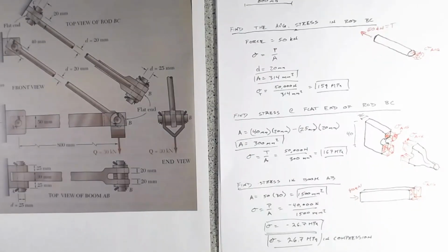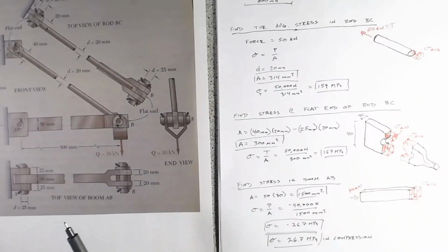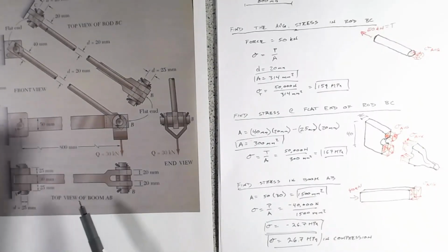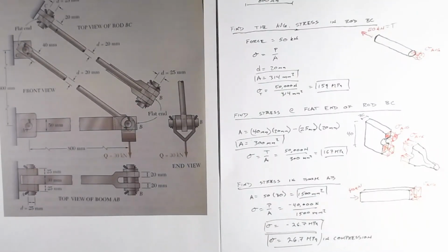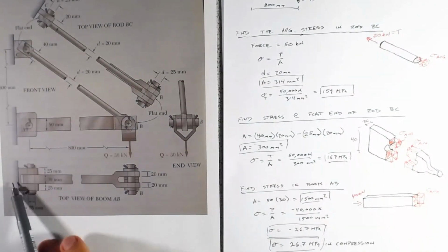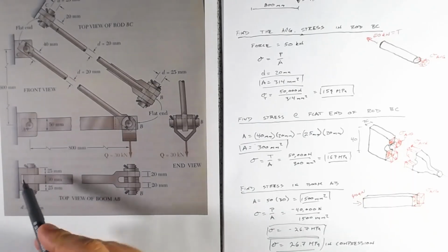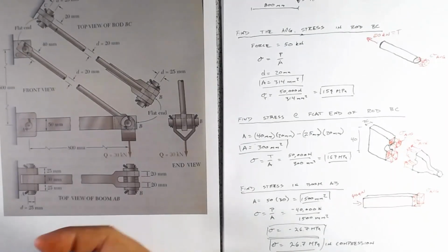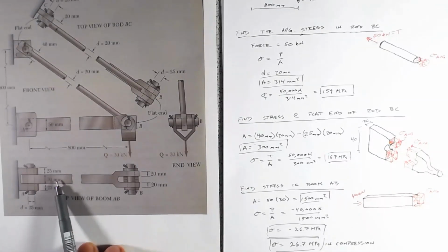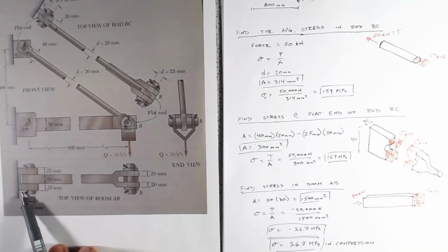And those are equivalent there. So cool. Well, now we've found out what our stress is in really the main members here. Now we need to start looking at the connections. And so the first thing we want to look at is down here at A, where we have this member in compression, and it's going to be pushing on this pin. So we've got to get the force, this compression force, into this reaction somehow, and it does that by pushing on the pin, and then the pin acts in shear and then pushes on this clevis.